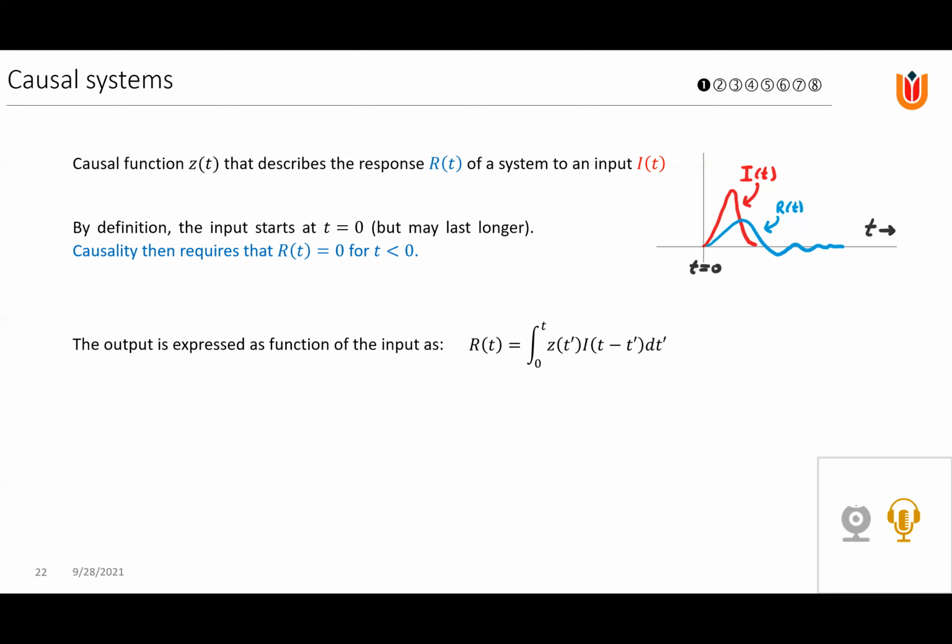So what you will get is probably something that is also an oscillation, but with an amplitude that is a little bit less. I'll draw it just in a moment. A little bit less because of losses in the system, but also it lags a little bit, because of this resistor it takes time to charge this capacitor, and it also takes time to discharge it again. So you will get an output that, it's going to be difficult to draw on the same scale, that is less in amplitude and a little bit lagging in phase.